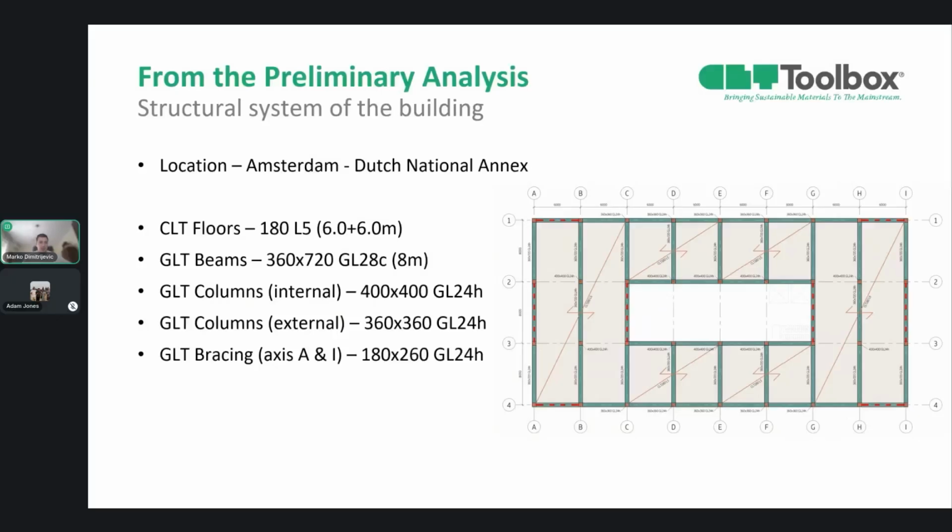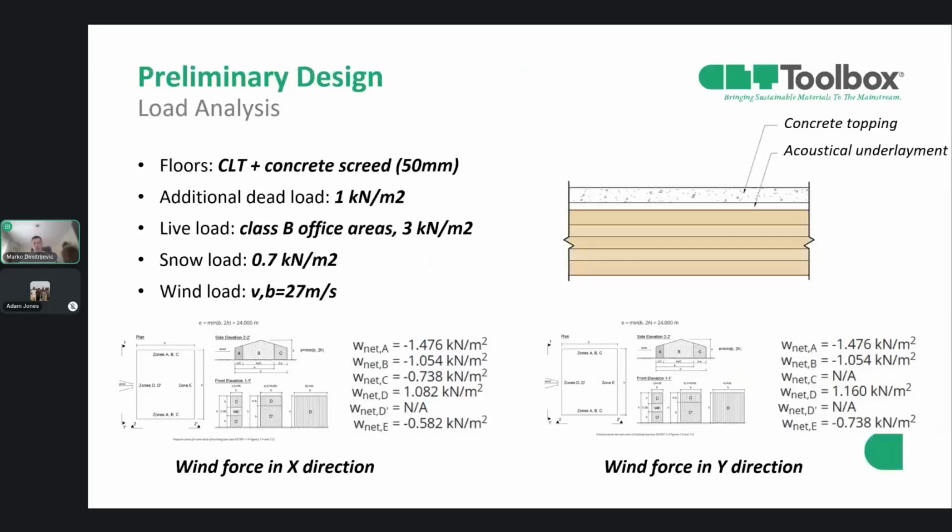And here is a recapitulation of what we designed in the previous webinar. So we have floors of CLT 180, 5 layers. We have beams, dimensions, columns, dimensions, and so on. We're going to start with the fire design of CLT beams.